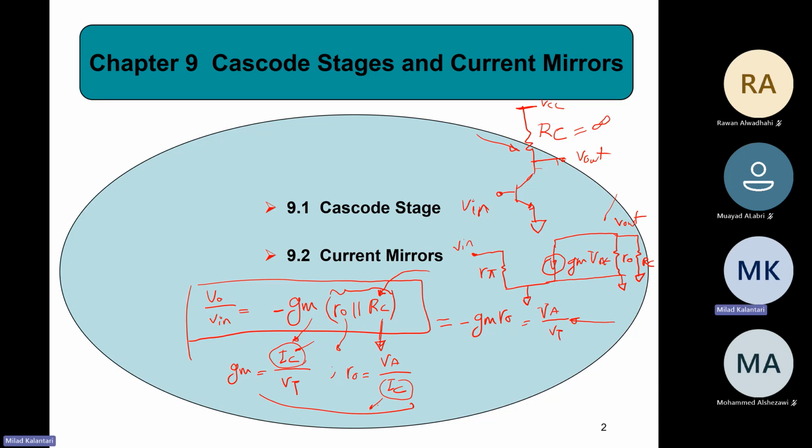And then the collector voltage, because the VCC is some constant fixed value, right? You put some 5 volt, for example, and you try to bias the device with certain current, like 1 milliamp, right? Then if you increase the RC, this collector voltage starts dropping until the device goes to saturation, right? So it's not practical to increase the RC too much.